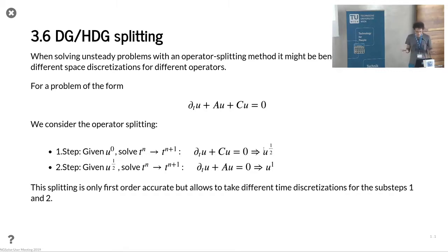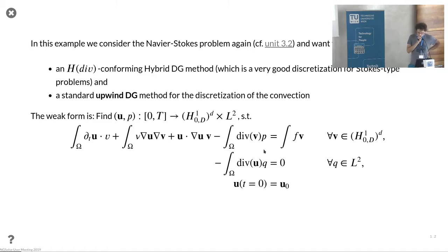Okay, so this is not the best discretization that you can do, of course, but this tutorial is meant to show some components based on this discretization. For the discretization, we also want to do something more fancy than just Taylor-Hood. So we use something which is HDiv conforming, because HDiv conforming is very cool. It's very nice, has very nice properties, and especially for Stokes and Navier-Stokes, there are very nice properties which lead to certain robustness and